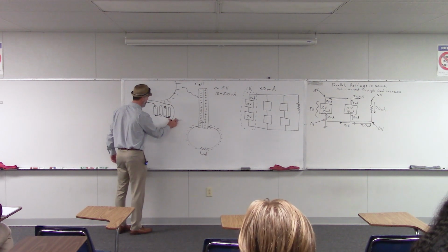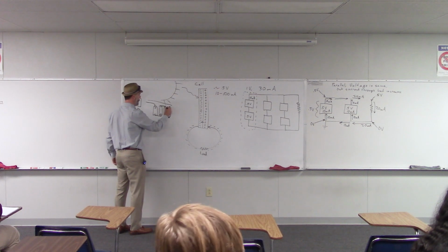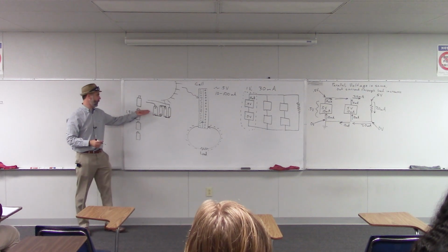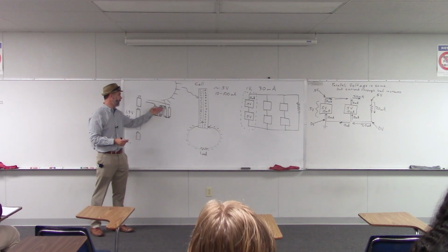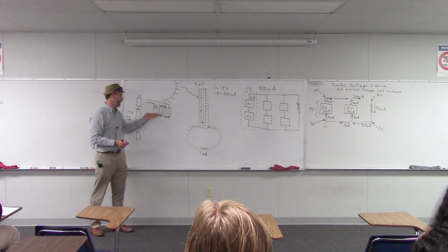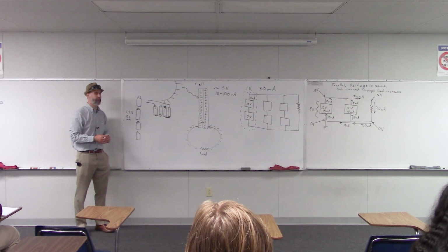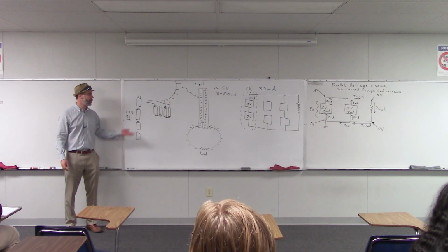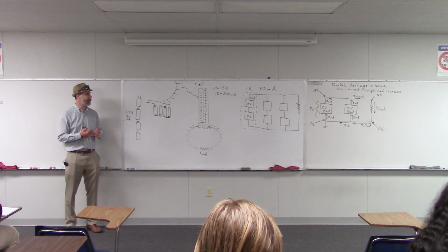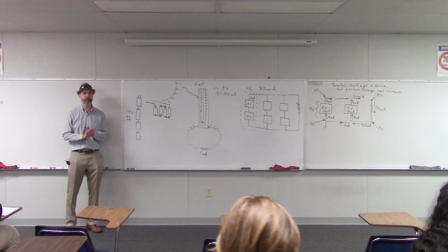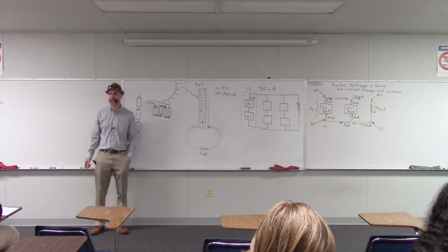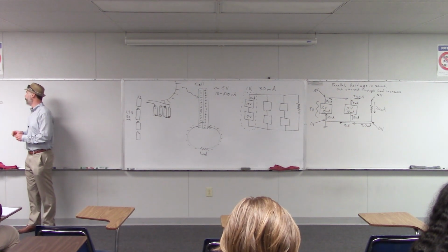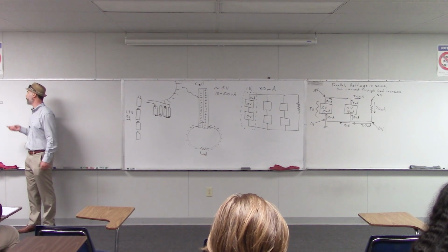There'd probably be one more connector there, and then the other wire would come out there. So yeah, you've connected the positive end of one battery to the negative end of the next, and you've done that for all 4 batteries, so that increases the voltage of your circuit there. Okay? So the same logic applies for cells, for panels, and for batteries. So any questions about that? Okay. All right. So that was our review of solar energy. That's what I wanted to say about solar energy.